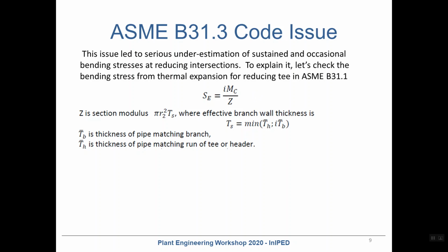To explain this problem, we need to first check the expansion range calculation in another code, in ASME B31 code. Here is that equation. This is the expansion range stress that equals the bending moment divided by section modulus and multiplied by the stress intensification factor.